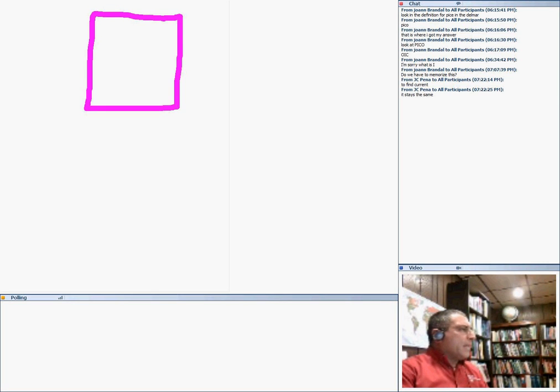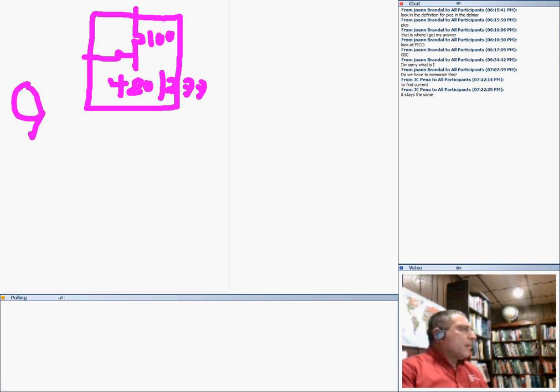What does that mean? Here's my 100 amp panel, and this panel is a 480/277, 100 amp. And look what I got. I have my three phase. Here's my pump. I'm running my pump with a three pole circuit breaker here, and this pump is taking, say, 30 amps.